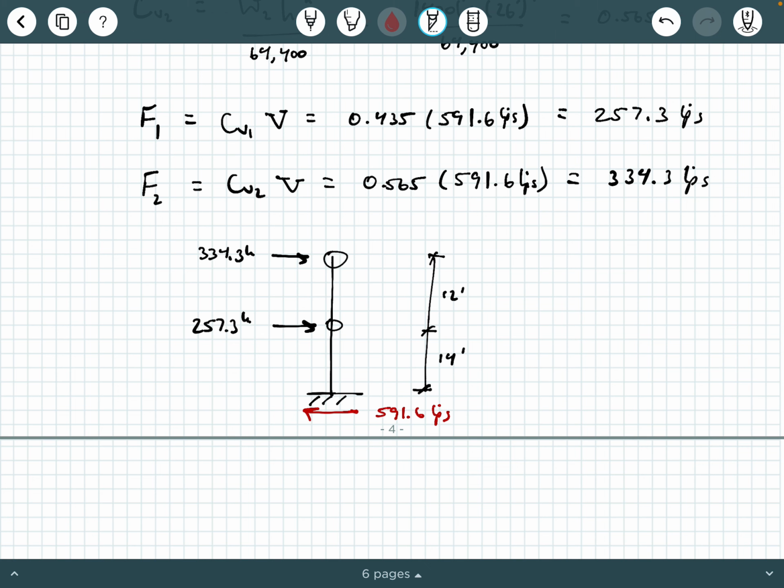Now, from here, you can do all kinds of cool structural analysis procedures. You can make a cut here and do method of sections, and you can get an internal shear force. In this story, we call that a story shear. You could do the same thing here, get an internal shear force here. You can get a moment reaction down here.